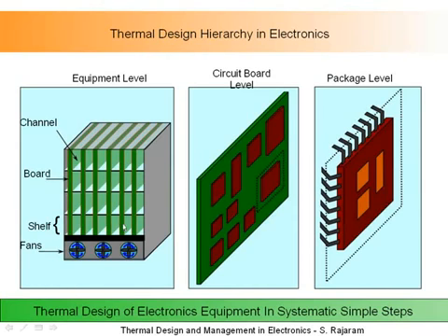You can have these, each one is a shelf or a rack. In each of those racks, you will have a board. Each of these boards will have multiple devices, and each of those devices inside will have many power generating transistors or areas. And normally in a system like this, I'm showing a system which uses fans. The fans will blow air in the channel between the boards. So essentially you have air flowing over these boards and cooling them.